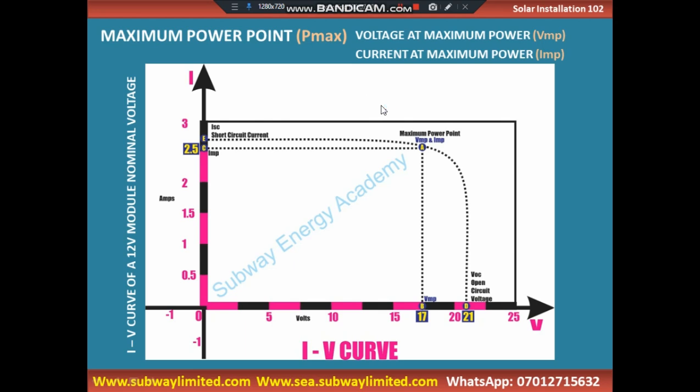So please, when you see the maximum power, that is the wattage rating of any solar panel that is on the nameplate, get to understand how they come about that maximum power and get to understand how those figures on the nameplate came about. That is what maximum power points, voltage at maximum power, current at maximum power mean.